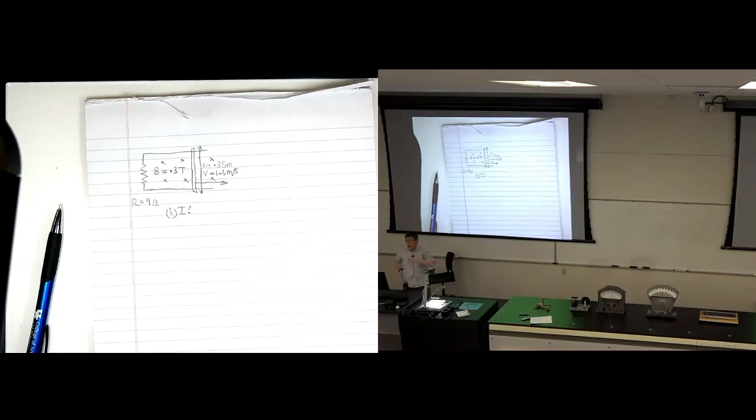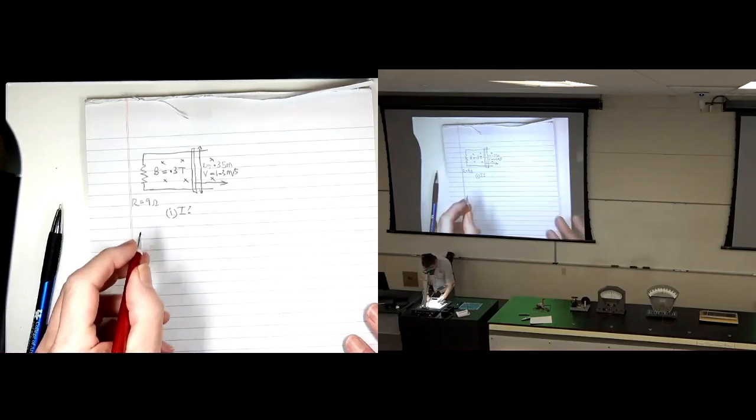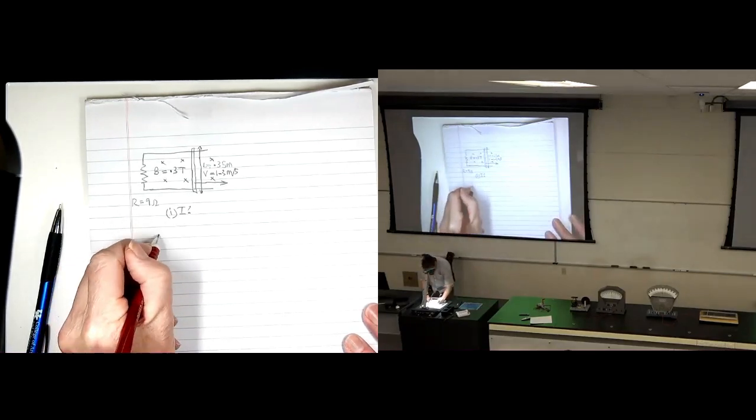And the second one, the new one for us, is Faraday's law, as applied to the linear generator: the induced EMF, that voltage that's induced, is equal to BLV. And so I'm going to combine those two laws. So let me start that going.